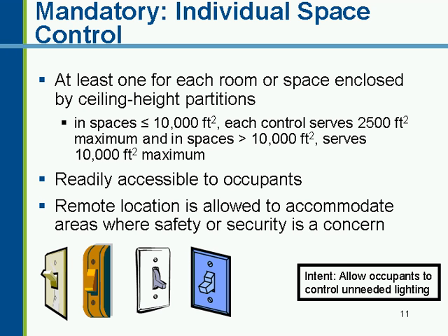It's a fairly basic requirement, but there are limits in terms of how much can be controlled by each switch. So in a space that's less than or equal to 10,000 square feet, the control can serve no more than 2,500 square feet for each control. So if you have a 10,000 square foot space, you're going to require at least 4 controls. If your spaces are greater than 10,000 square feet, that limit moves up to 10,000 square feet.